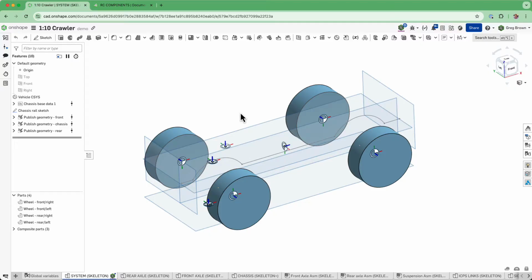You can version manage this thing because it's a composite part. You can release manage it. That's a really, really powerful thing. I won't go into too much today, but release management of the composite part, which is carrying the references, is a hugely robust way of doing things.